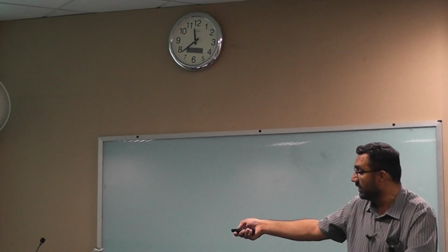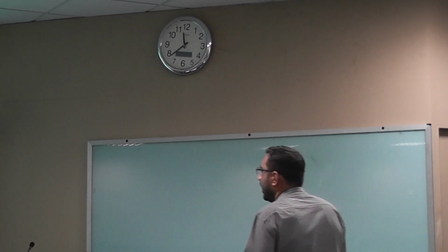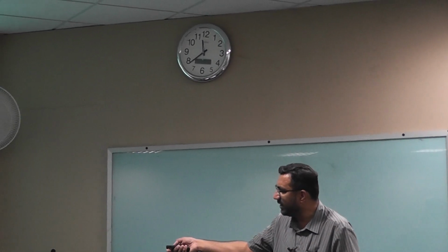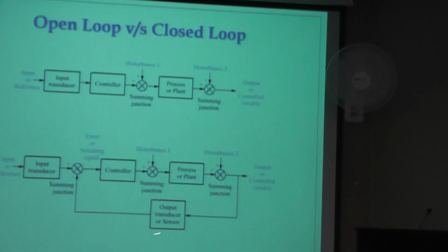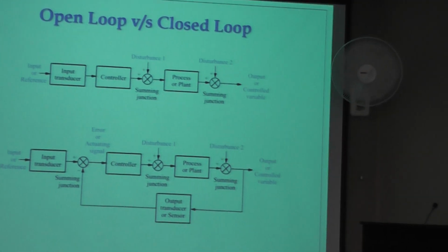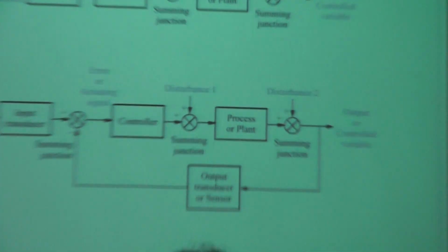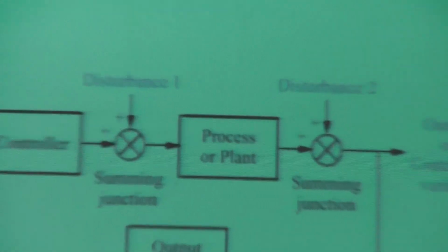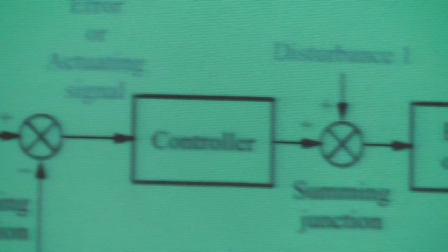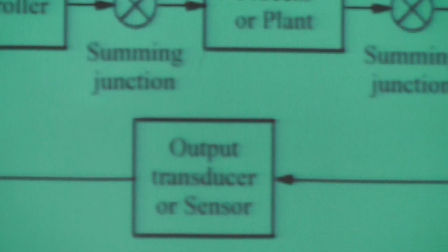So that's why this system is better than that system, of course, because it can take care of disturbances and it can still give you the output response as expected. But it has a disadvantage as well. This channel here, if this is not a good gain, usually we look at unity feedback systems because both theories are based on unity feedback systems. But if this is not a good gain, it can actually do the worst thing.